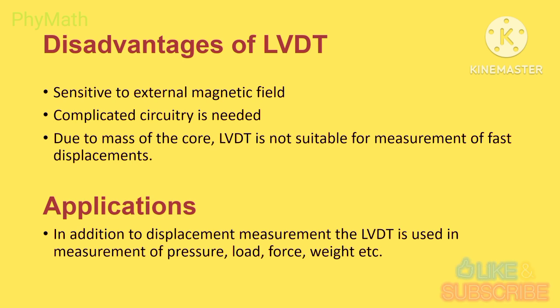Now, what are the different applications of LVDT? In addition to displacement measurement, the LVDT is used in measurement of pressure, then measurement of load, then measurement of force or weight, etc.